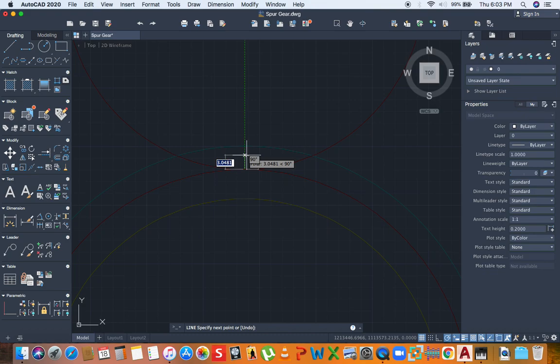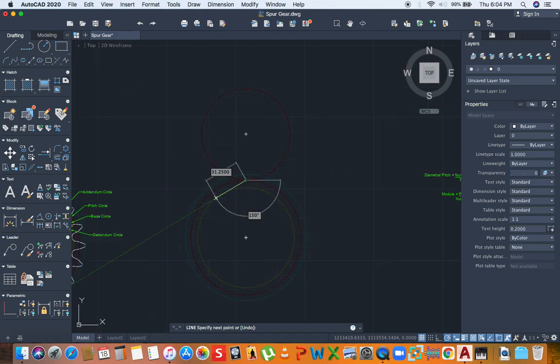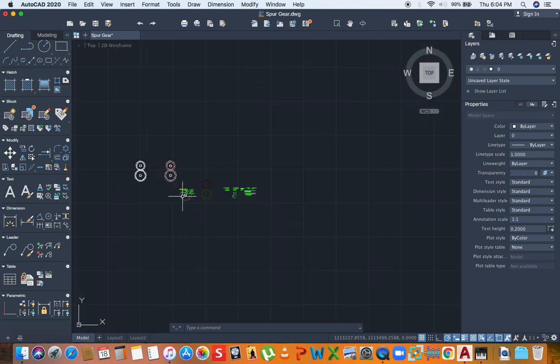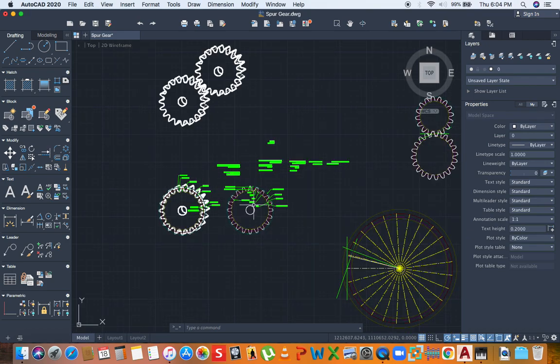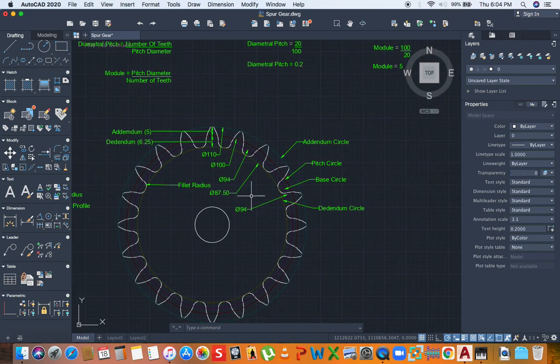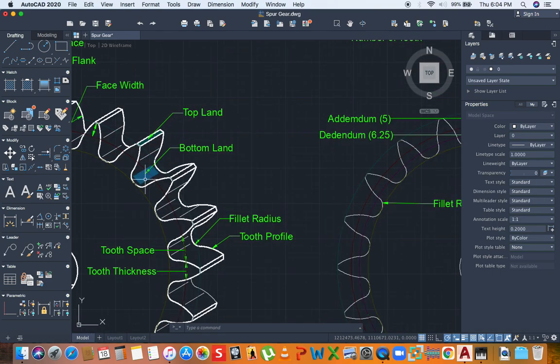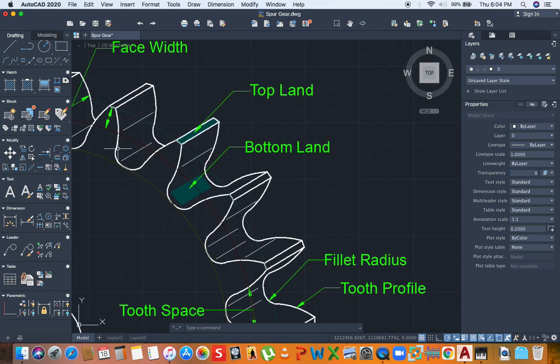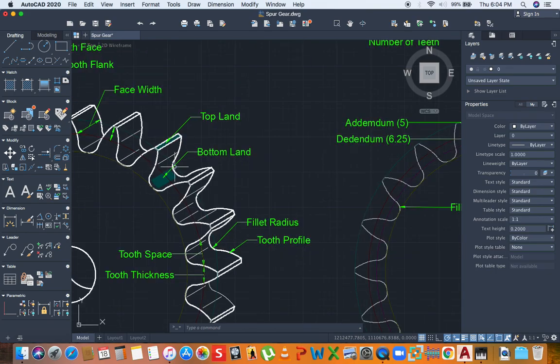Once the backlash is 0, the gear will be susceptible to wear and tear because the teeth will be grinding against each other in a way that you don't want. The teeth have to touch to give the motion, but you don't want them to be touching on both sides. Let me show you what I'm talking about. You want some clearance. That is the term that is used. The teeth are not supposed to touch the bottom land. They are not supposed to touch even the fillet curve.